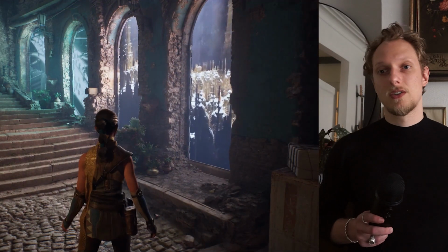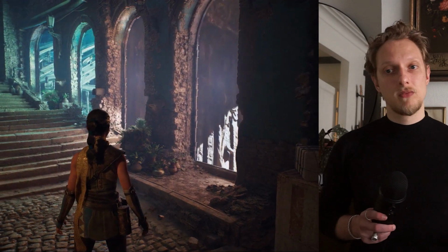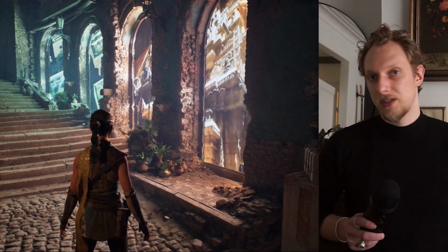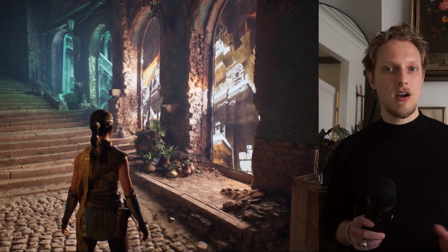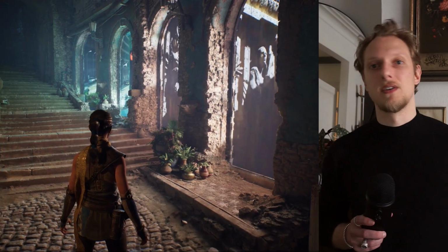Yes, MegaLights allows for many lights, but remember, you have to take care of your overlaps. MegaLights also supports textured rect lights and complex layered materials. These add some tile classification overhead, but they work correctly. Just be aware that a textured rect light is the most expensive light type in the sampling pass.